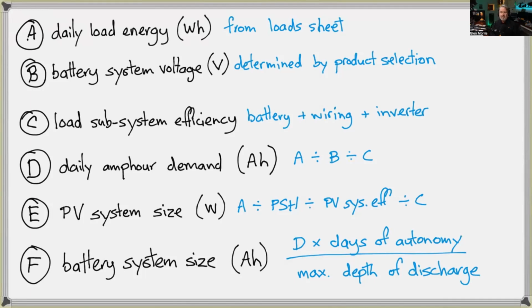Now that depends on the type of battery you've got. Modern lithium batteries are very efficient, the high 90s. But a lead acid battery, for instance, even when it's new, is only the high 80s, and it deteriorates with age, so you can end up with quite poor efficiency. Some other chemistries have quite low efficiency because of their design. So you need to understand what that is. This is something you would get from the manufacturer. So the round trip efficiency is expressed as a factor, and I think I put some numbers in there.